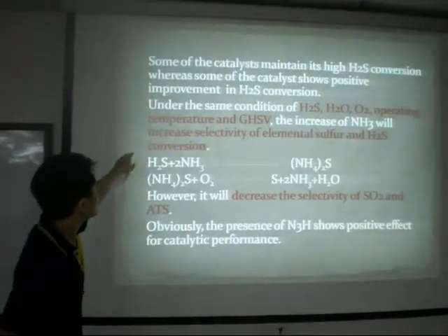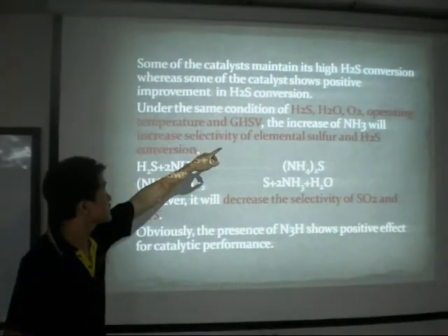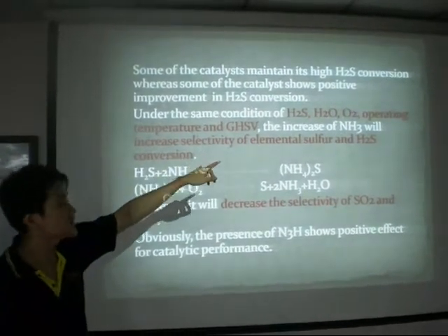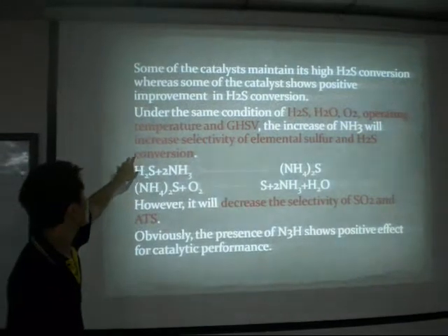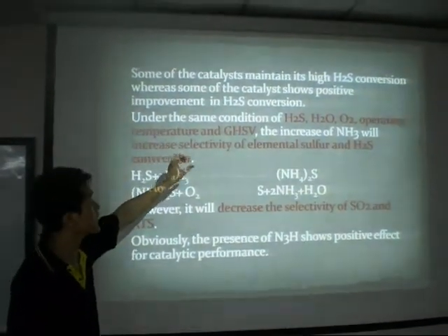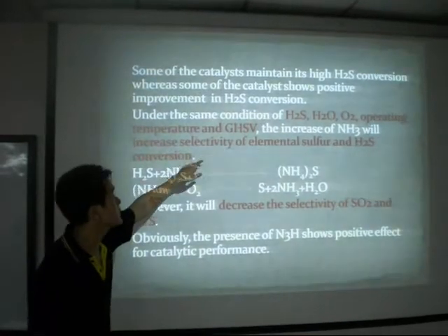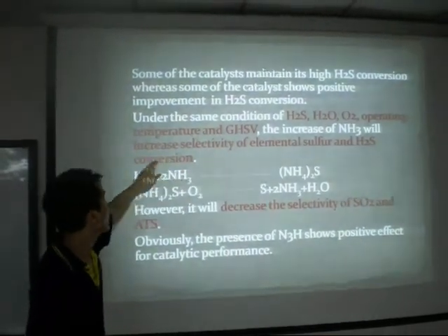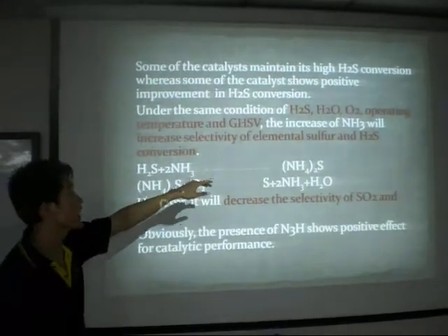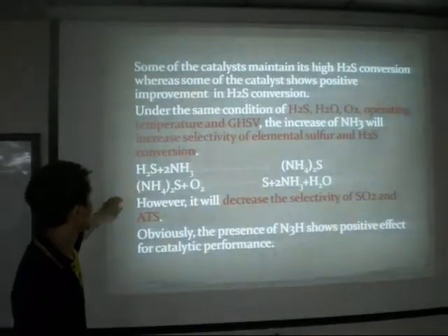Under the same conditions of H2S, H2O and O2 concentration, operating temperature and GHSV, which is related to contact time, the increase of ammonia will increase the selectivity of elemental sulfur and H2S conversion.